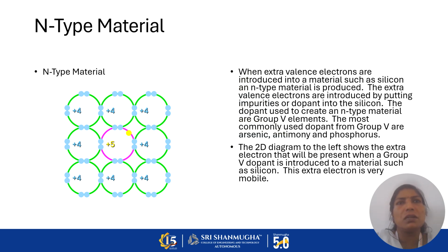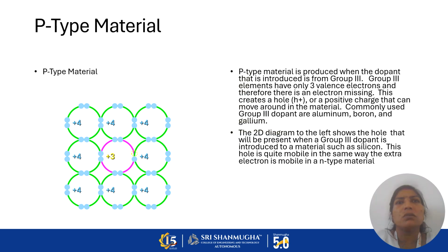Next, the depletion region is the region where there are no free charge carriers. This region acts like a barrier and prevents current flow in normal condition. It creates a barrier voltage. For example, silicon diode barrier voltage is 0.7 volt and germanium diode barrier voltage is approximately 0.3 volt.